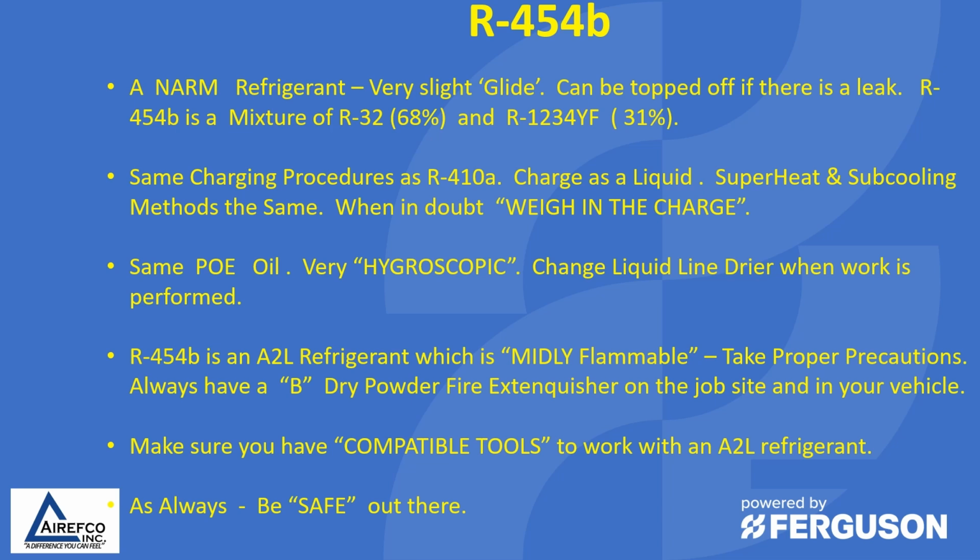R454B is an A2L refrigerant which is mildly flammable. Take proper precautions. Always have a B dry powder fire extinguisher on the job site and in your vehicle. Make sure you have compatible tools to work with an A2L refrigerant. And as always, be safe out there.